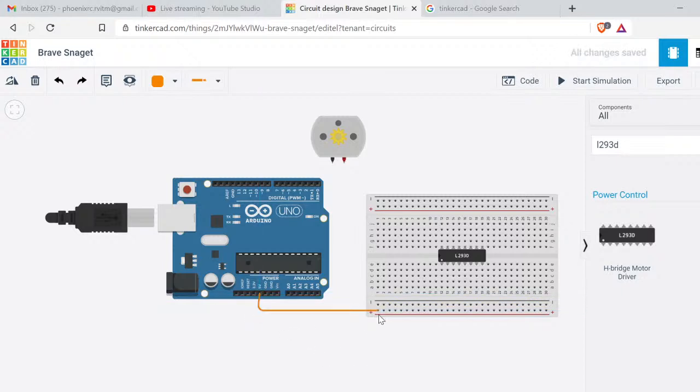So all the pins here in this row, horizontally, will be 5 volts. And if I take negative, I will connect to ground, and all the pins in the negative column or negative row will be ground, and the alternates will be 5 volts. Same thing here on left and right. But when I come to the middle, these alternatives will be vertically equal.